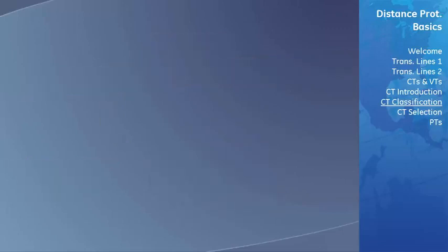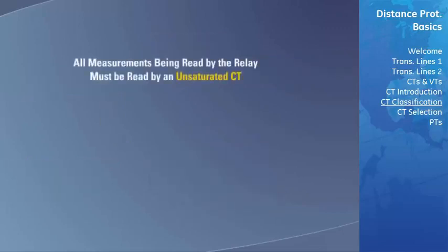It is imperative that all measurements being read by the relay are read with an unsaturated CT. To accomplish this, appropriate CT selection must be made to ensure the rated CT can handle the applied current without saturating.